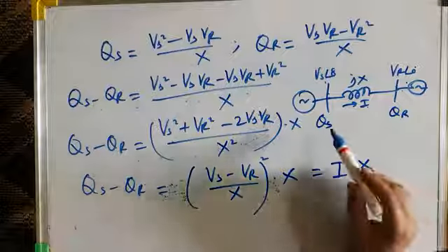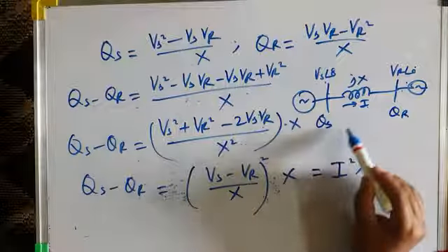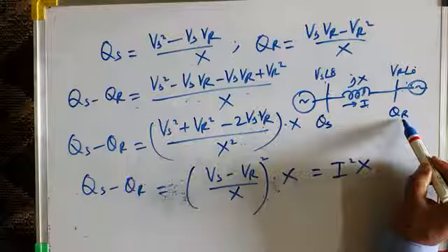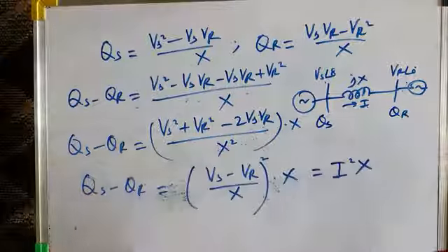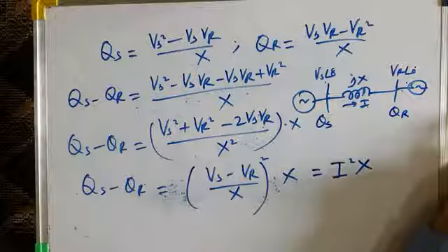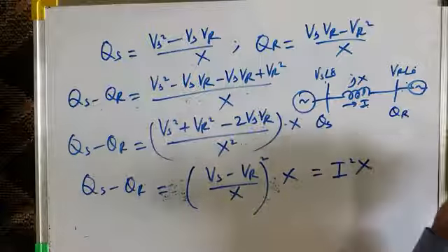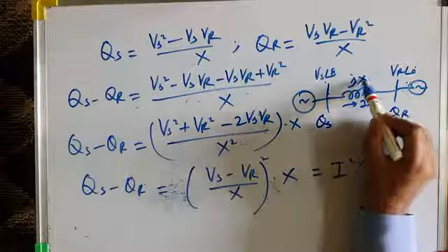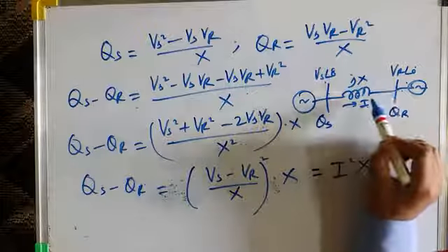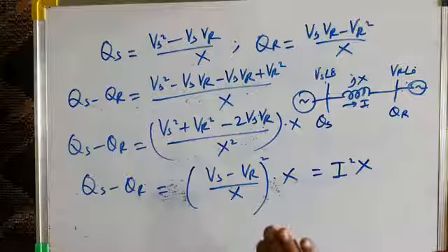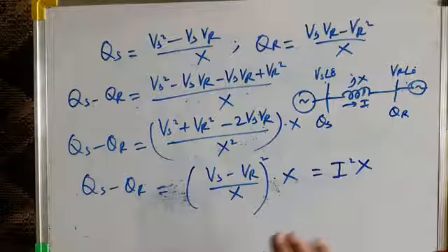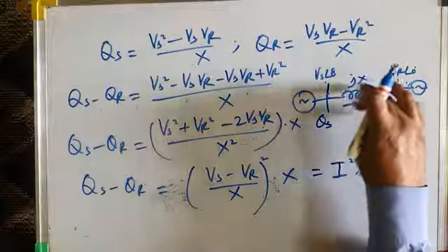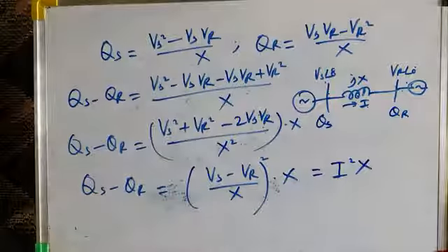That means that the reactive power generated at the sending end and at the receiving end, most of it is absorbed by the load. It flows over the transmission line and is ultimately absorbed by the load. But the difference between the two reactive powers is absorbed by the line reactance. So there are two types of reactive power in any AC system. One is the reactive power demanded by the load, and another is the reactive power due to the line reactances, due to the system reactances.